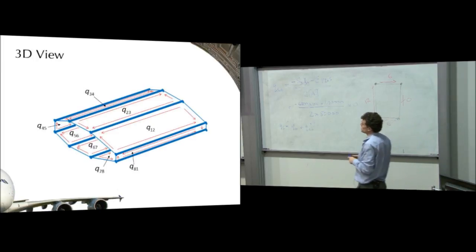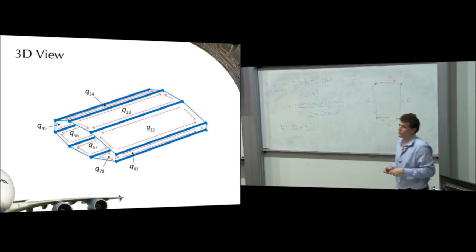And we'll do some examples of that in other lectures where instead of assuming that the longitudinal shear flow is constant, we'll vary it by varying the forces in the booms. So if we start applying other forces to the booms, we can start working out what happens to the shear flow in those panels. And so we can build up more complicated structures that way.